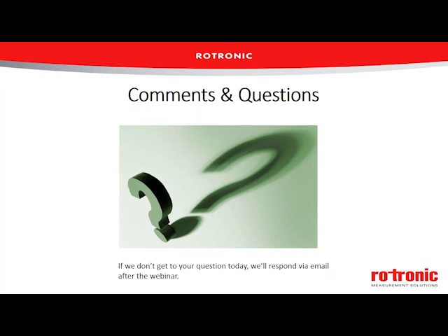On a chilled mirror, if you've got a large buildup on the mirror, that's going to look the same as dew or frost to the light sensor. On a capacitive sensor, it could slow down the response time, or the bacteria may actually bring more moisture to the sensor, making it seem like the relative humidity is artificially high. So in both cases, there's a potential effect that could be seen.